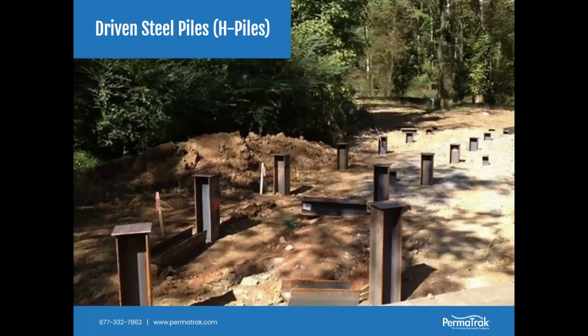Driven steel pile, and I've got two slides, and then John Pyle will take over. But a driven steel pile sometimes is required. The capacity of a driven steel pile and a driven concrete pile is far too much for what is needed vertically for a boardwalk system. Boardwalk loads are going to be typically 5 ton, 10 ton, maybe 20 tons. And these type pile systems, you might typically see on highway and vehicular bridges.